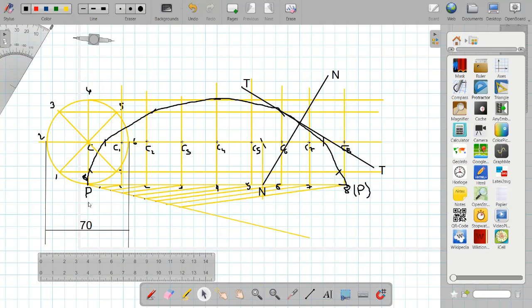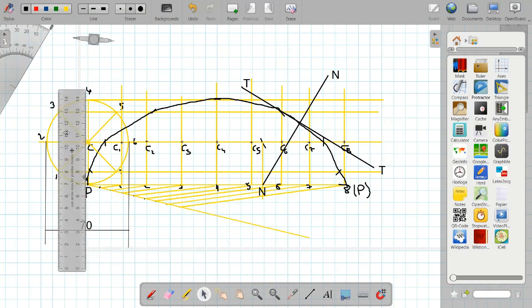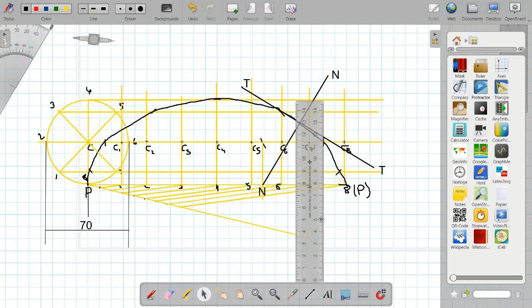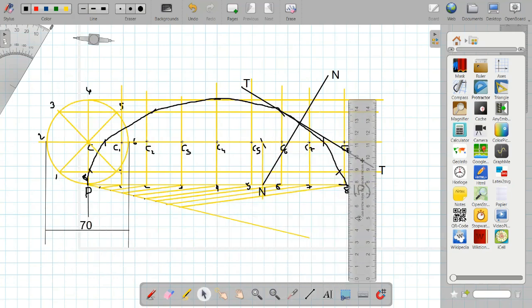And then we have made this part as the circumference, that is 2 pi r. So I have to make that dimension also, the dimension for this line. Again, it should be medium, not light, because it's a dimension line. This point, and this one.